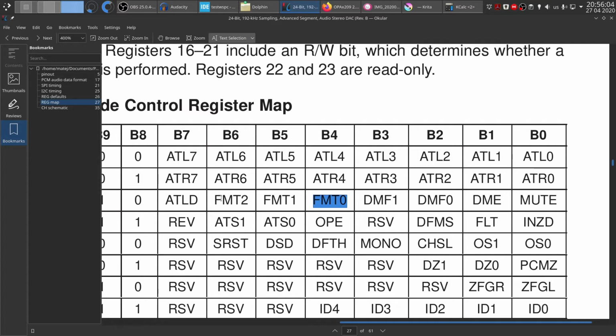If you just wrote 1, 0, 1, of course 0, 0, 0, 0, 1, 0, 1, 0, into register 18, we would just overwrite all the other settings. Let's say this was 1, and this was 1, and let's say this was 1. If we just applied the configuration for these 3 bits, we would erase all the other configuration over here, or actually force it to 0, which is something we might not want.